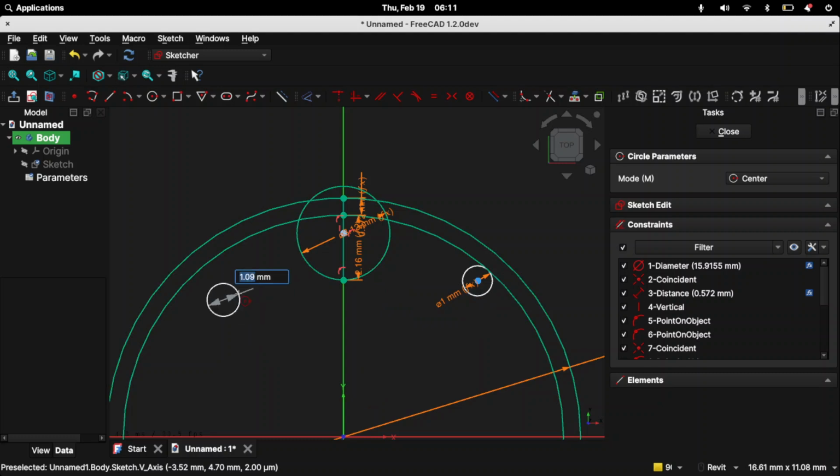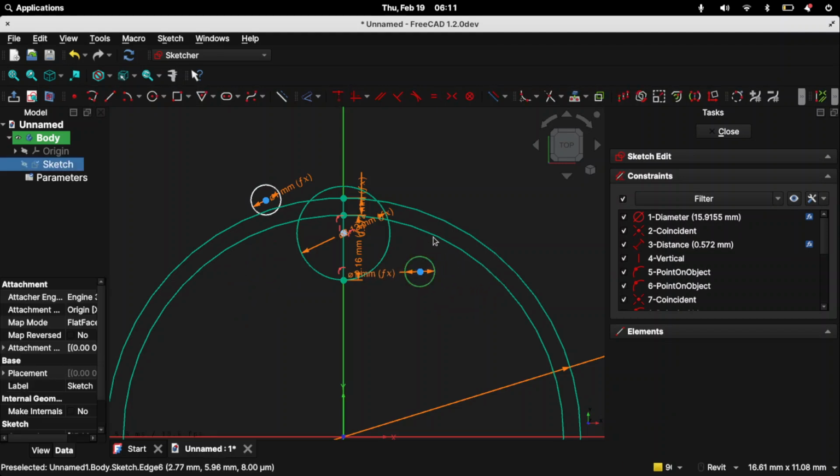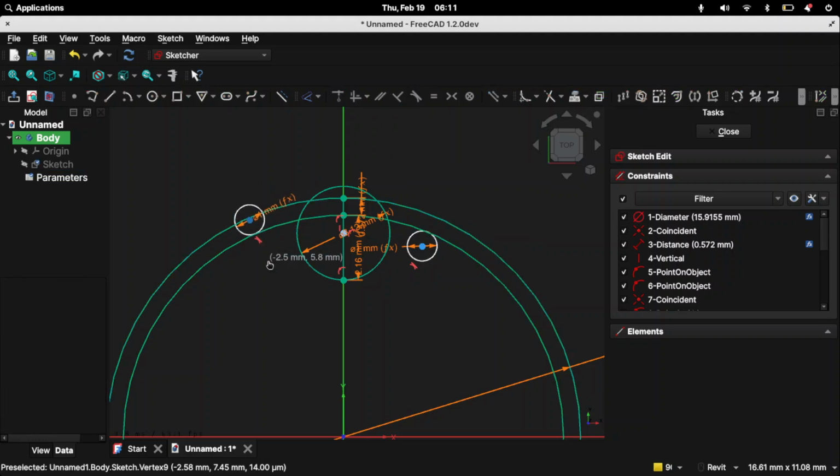And if I reference that, I can say HTD-2, and it automatically grabs that dimension from the spreadsheet. So I want these to be tangent to the inner diameter on the other side.